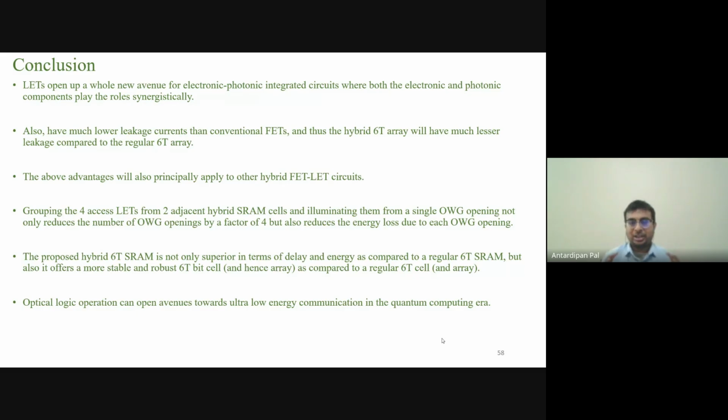Yes. Our structure is very energy efficient. It has extreme lightning speed. It cannot be miniaturized. It means you cannot have this structure inside your mobile phone. You cannot have these inside your smartwatch. Because the optical part takes up lots of space. You saw it, right? If we scale down the optical waveguide to 100 nanometers, it does not transmit at all. It's bad. So we need a minimum of 400 nanometer by 400 nanometer cross section for a single waveguide. So it takes up a lot of space.